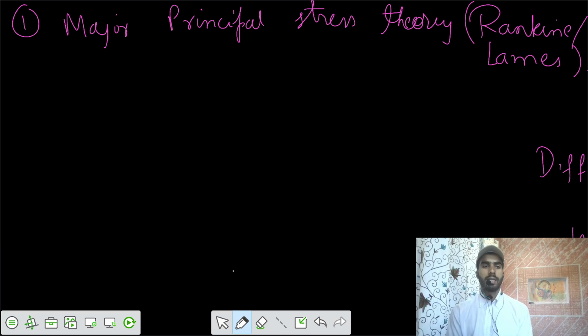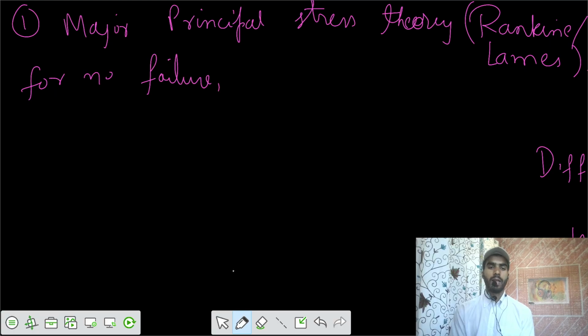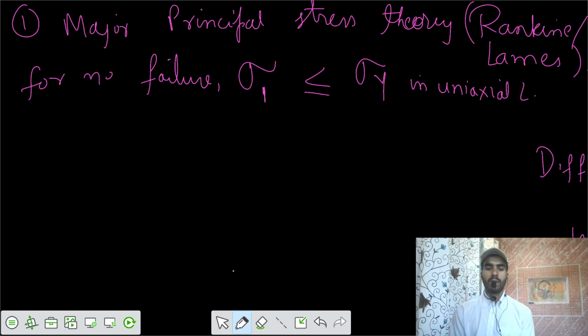They say that for no failure to happen, your major principal stress should be less than or equal to the yield stress in uniaxial loading. So we can write that. They compare the major principal stress that has developed in multi-axial loading with the yield stress in uniaxial loading.